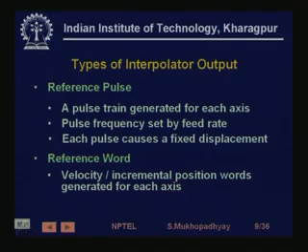So you are giving a single bit, so the interface is a single bit which is either 1 or 0. On the other hand, you have a reference word system where you actually send the whole coordinate to the motion controller and say achieve this velocity or achieve this position in x and y. So in one case you are sending a multi-bit number, in another case you are sending pulses, and the sum of the pulses indicates the motion that you want to create.